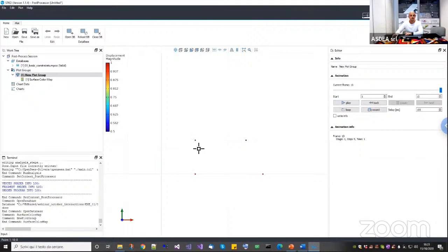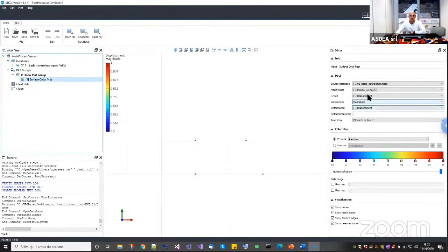Okay. So basically, when you have an equal DOF, they will move exactly in the same way. But in this case, it will move the same way as the master node plus rotations times a distance. Now, in this case, it will be +1 minus 0.5. Okay. And this one, of course, is the X displacement. Let me go to the displacement and not magnitude, but only X. Okay. So this one is equal to 1, this one is equal to 0.5.